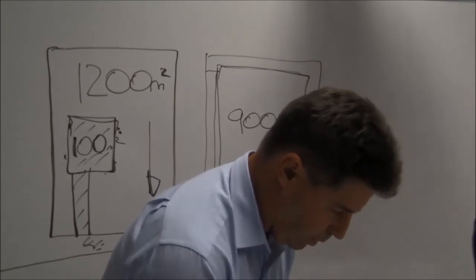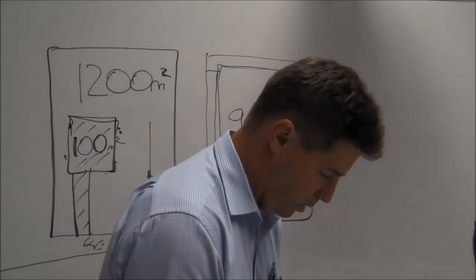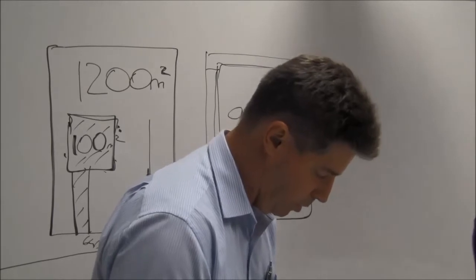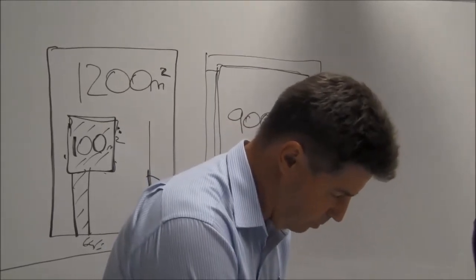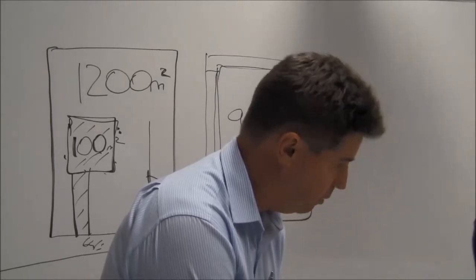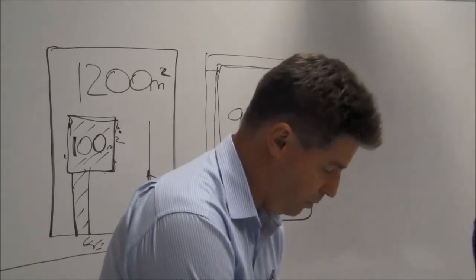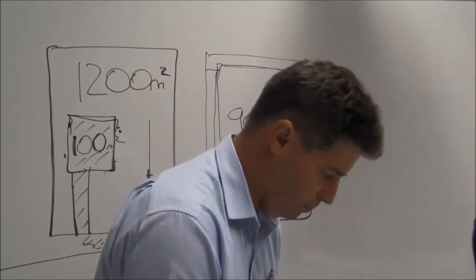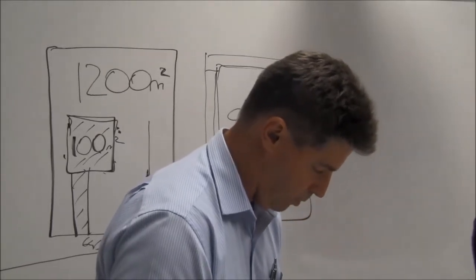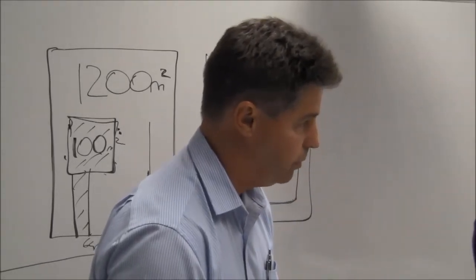So if we follow that through and onto the next page, all I've done is given you examples. Our 1 year ARI is our fraction impervious multiplied by the numbers out of table 2.2. So 1 year is multiplied by 0.8, 2 is 0.85, 5 is 0.95, and then 10 is 1, then 1.05, 1.15, 1.2. Just multiply it by those, and we end up with our final CY values for the discharge off the site, the runoff site. And pretty much that's all it is.